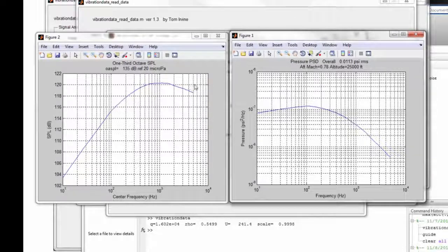Now those two curves look different. And the reason they look different is that this is a 1/3 octave presentation here, and in this case, our power spectral density is based on a constant delta F spacing. Of course, there's also a difference in our amplitude format. In this case, we have a density calculation, or the y-axis parameter is a density parameter, whereas the y-axis here is simply the overall energy within each band. So those are the two differences between this pair of curves.